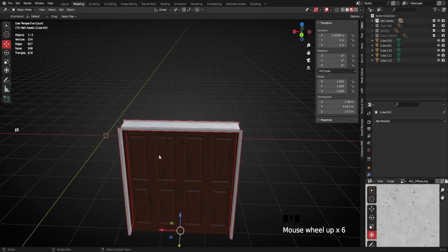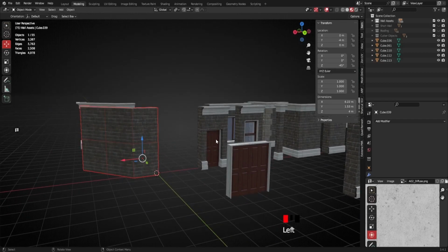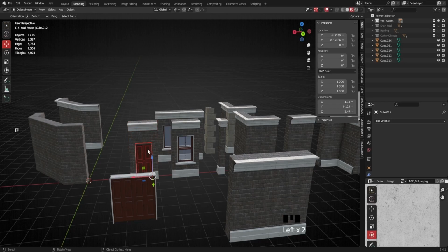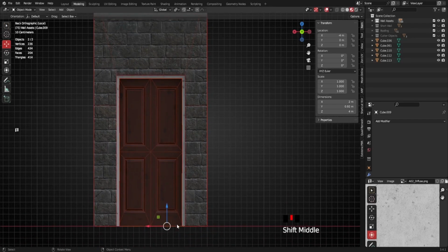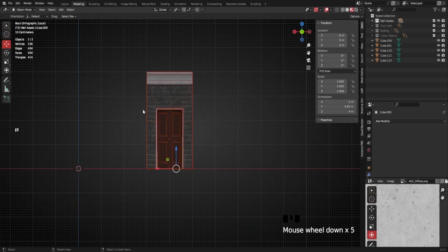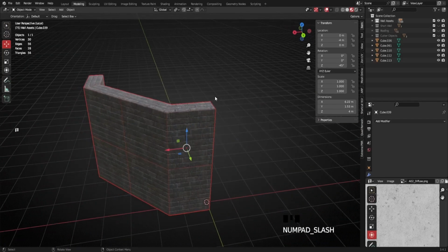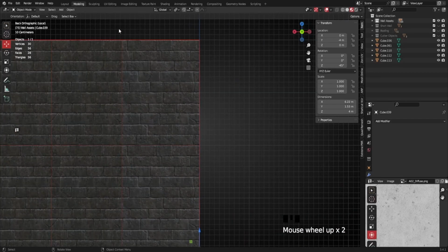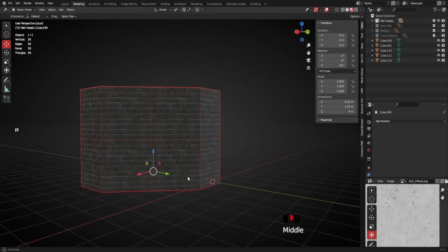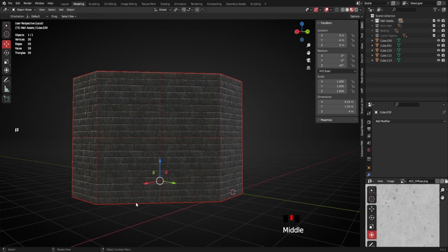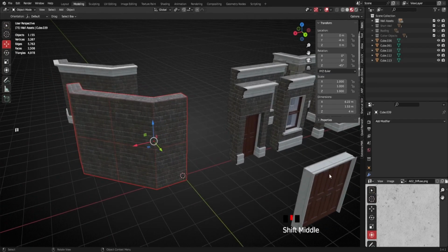It's actually important for us to line this up with the beveled wall, because this is a little less straightforward than this door was, or the windows. Because with these, what we were doing basically was just going into an orthographic, so a front orthographic or a side orthographic or whatever it was, and we were just knife projecting that hole in. But that won't work here with this wall, because we can't actually get to that. If we go front orthographic, we're getting this flat face part here, or we go side orthographic, we're getting the other flat face. We can't get an orthographic view of this angle. So in order to cut this, we're going to have to do something a little different. What I'll do is I'll copy this.